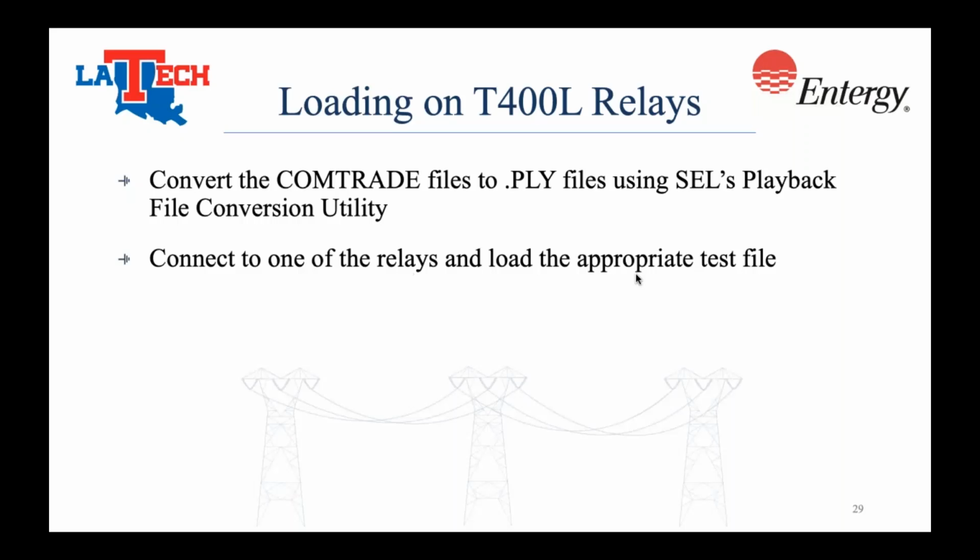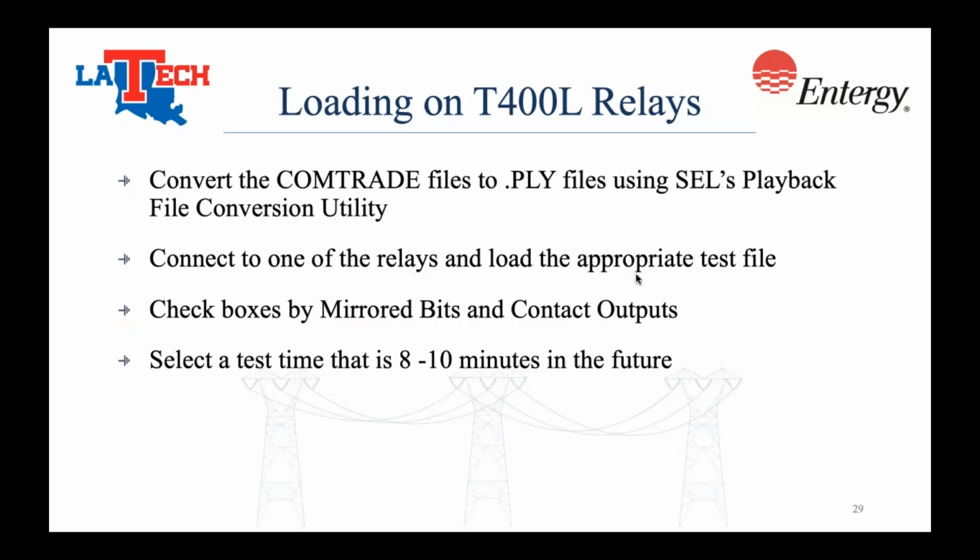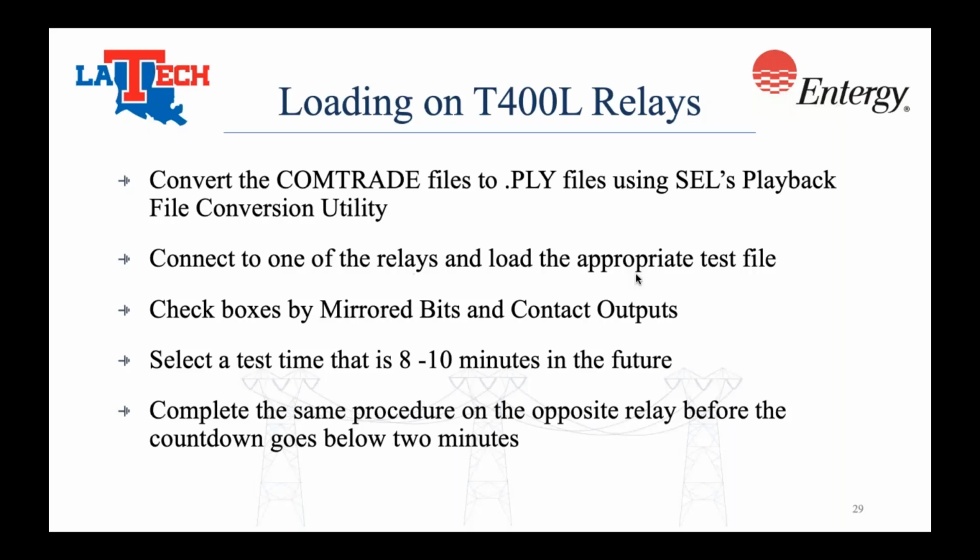In the playback dashboard, users can load files on the relay and initiate test cases. Users must ensure that the mirrored bits and contact output boxes are checked, and a test time should be selected that is 8 to 10 minutes in the future, because once the countdown reaches 2 minutes, no more changes can be made.